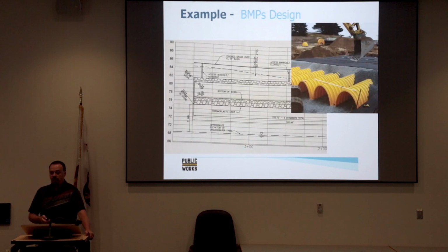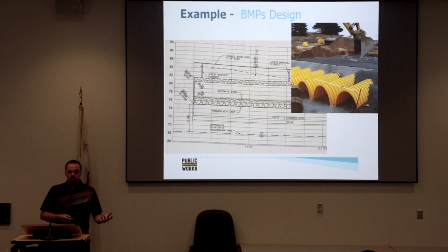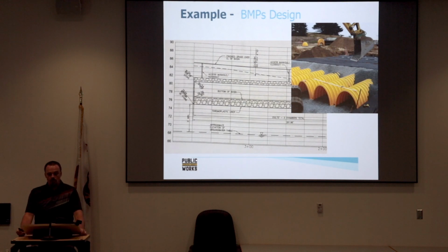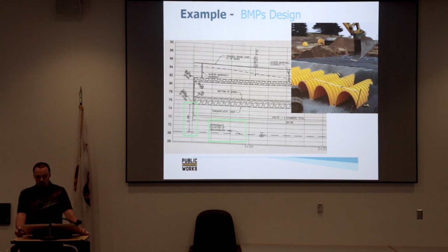So this is from the plans. This is the BMP they're proposing to do, which is a subsurface infiltration system. And a couple things I like about this: on the detail for the section, they do show the groundwater elevation that matches what was in the geotech report, showing that they're going to meet at minimum their 5-foot separation. And if you look at the side, it's actually about 6.5, almost 7, but they say 5-foot minimum is going to be met. So I know they're thinking about it, the infiltration's good.